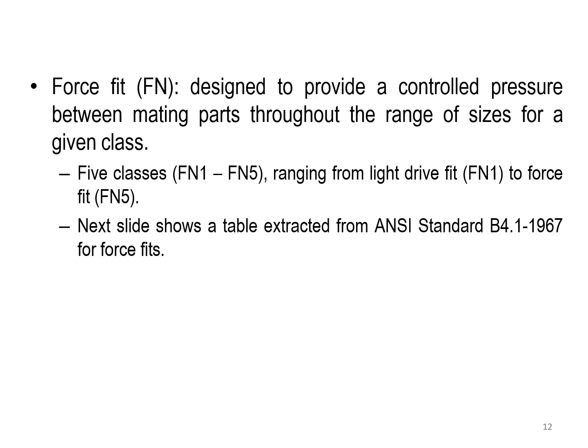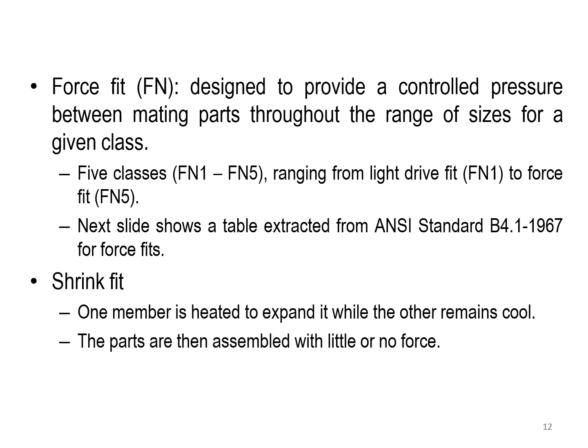We have the shrink fit, where one member is heated to expand, which is mainly the hole, while the other remains cool. Then the parts are assembled with little or no force. Also, there's another way: they can simply cool down the shaft and then put it inside the hole, where it will start to expand in size.